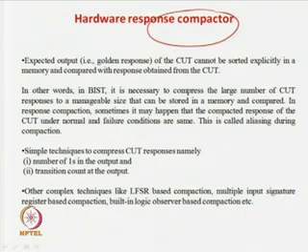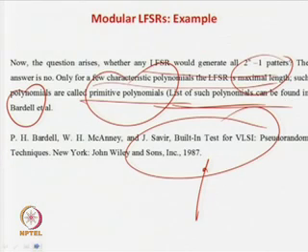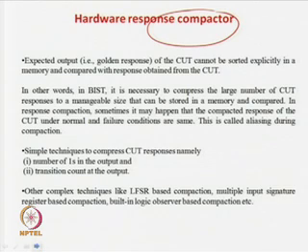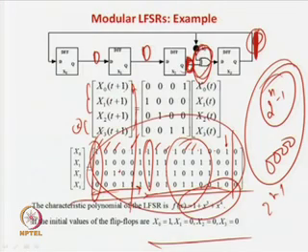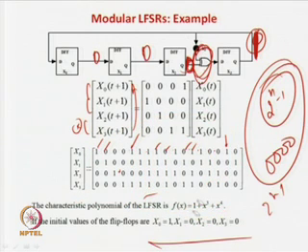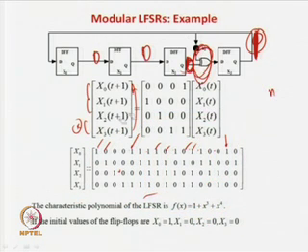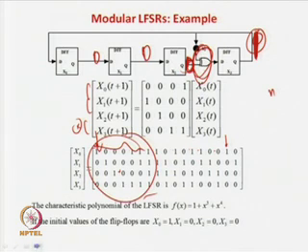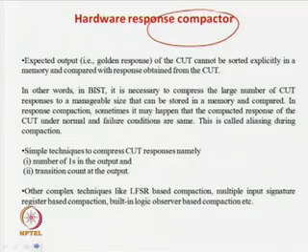The circuit will generate some responses based on your input patterns. Given this LFSR, you already know what pattern will be generated, and you can also easily compute what the normal response of the circuit will be corresponding to this pattern, because given a characteristic polynomial, the design is pre-made and already fabricated in the circuit. So we know the seed, we know the sequence of patterns that will be generated, and if the circuit is operating normally, we know the output response corresponding to each pattern. That can be calculated in advance, stored in a ROM, and compared.